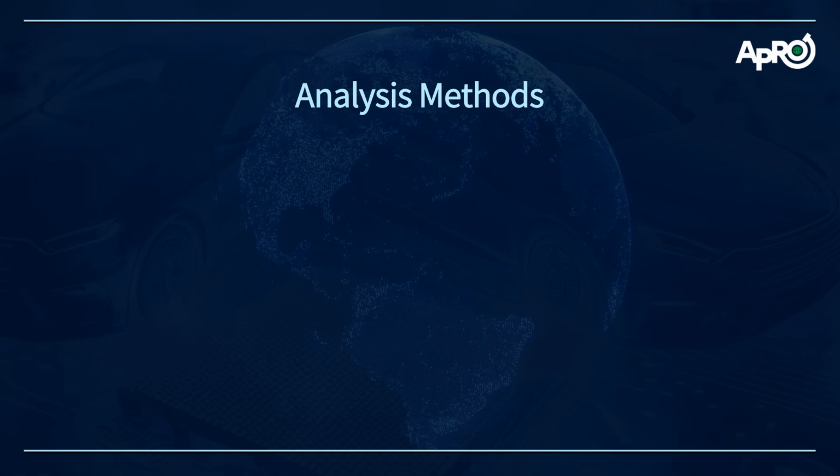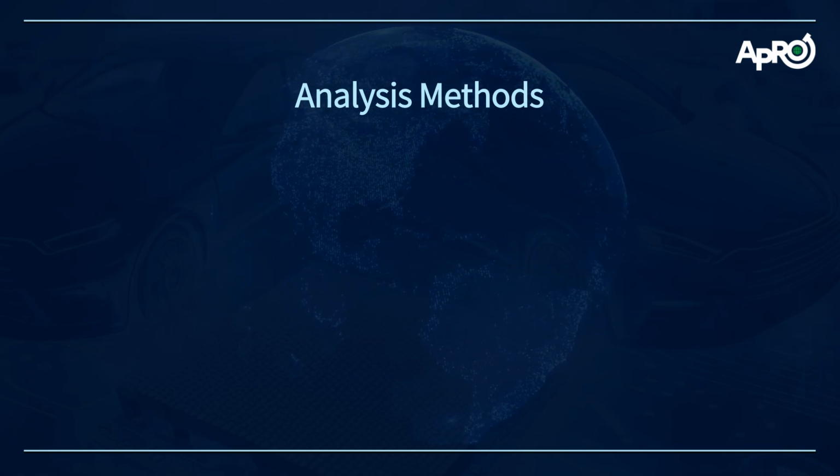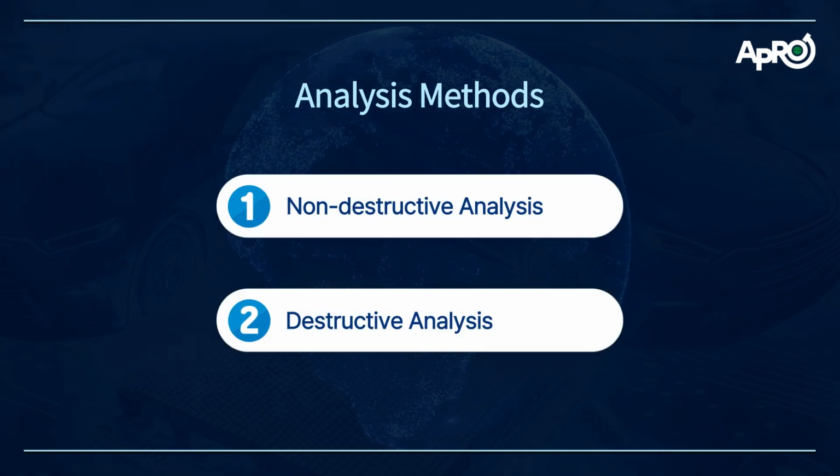However, due to the EMC material used to protect the internal components, such as the chip, it is difficult to check the internal state of the semiconductor. There are two main methods for examining the interior of these semiconductors. These are non-destructive analysis and destructive analysis.